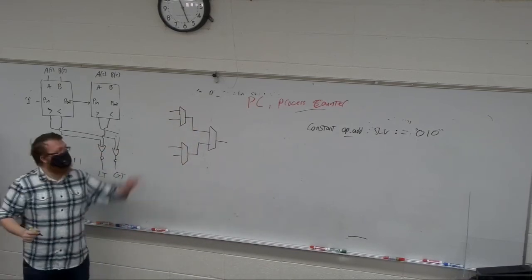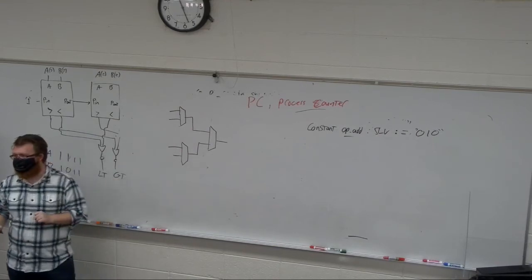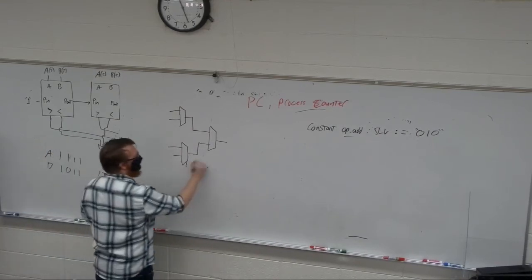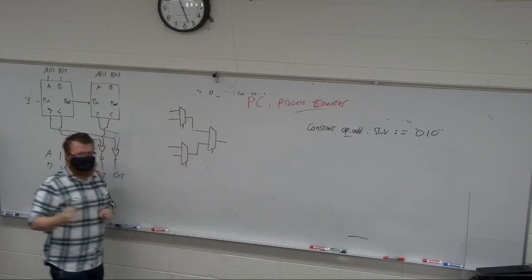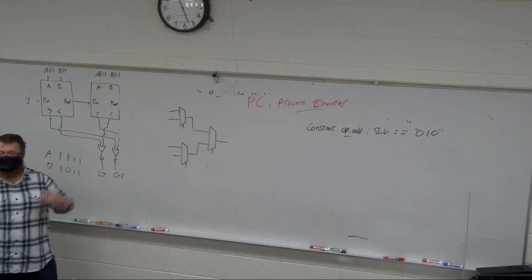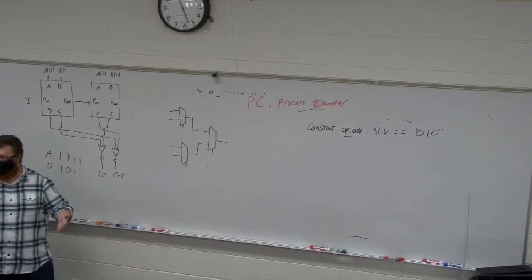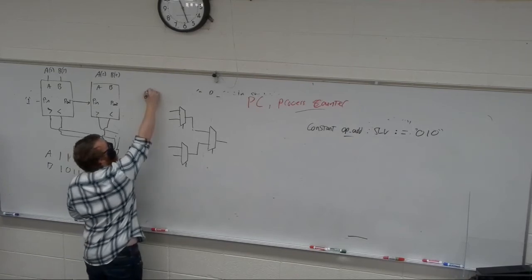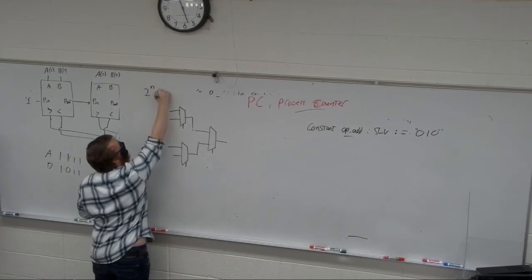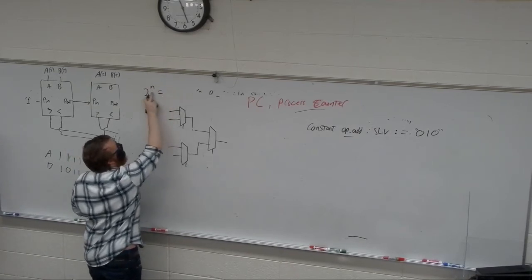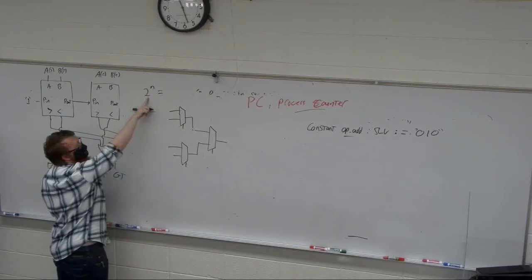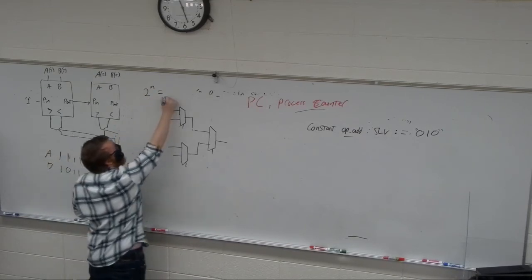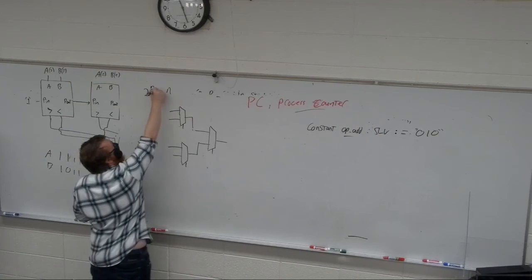I have 4 inputs, 1 output. Each of these has a select signal. If I have 4 inputs, I have 2 to the n inputs, so I need n select signals.